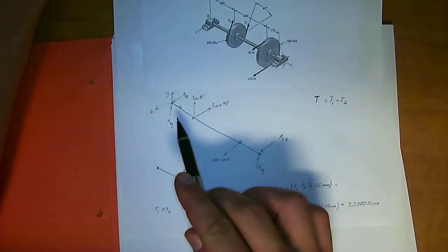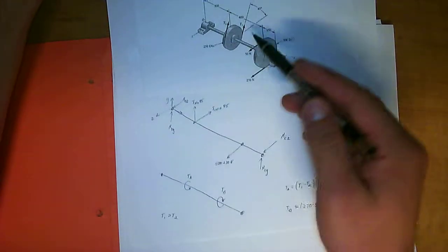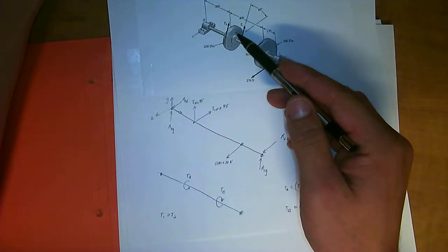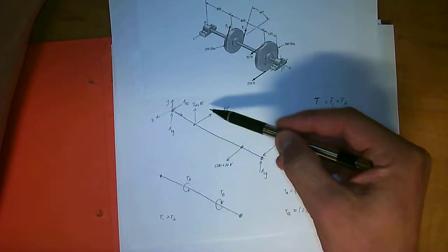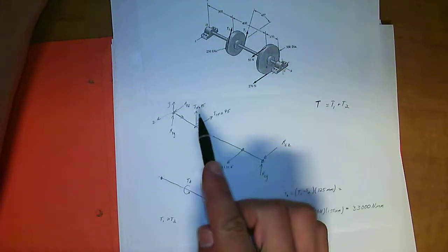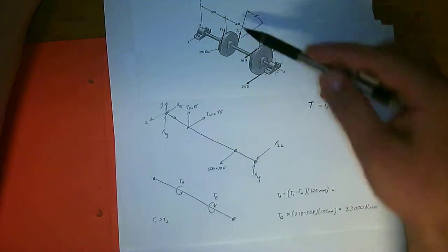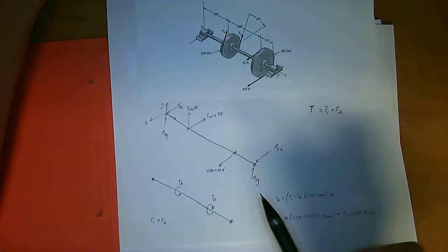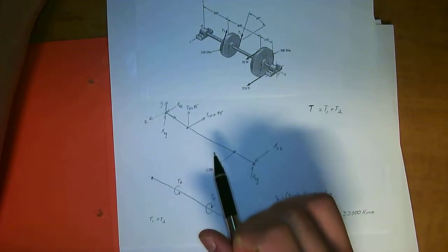Okay, so first thing I did was a basic free-body diagram, and plotted all the reactions. I turned the angled pulley tensions into their directions. The T here is actually a combination of T2 and T1, as shown over here. So T is T1 plus T2, but they're both going in the same direction, so I can say that. So I'll be able to direct those into the X, Y, and Z directions.